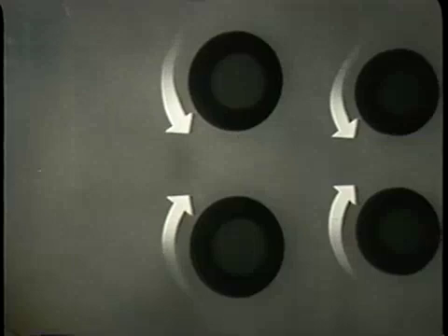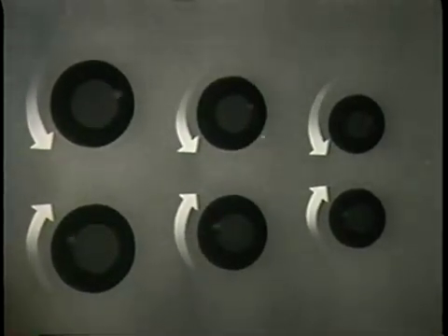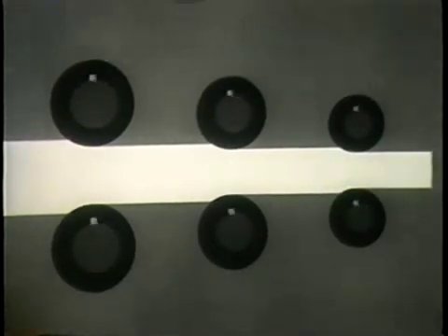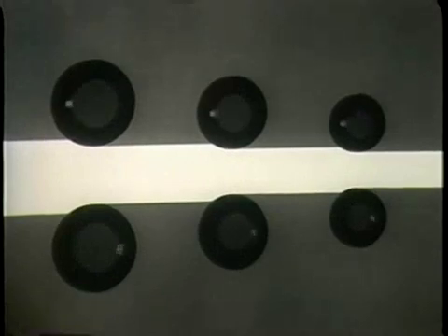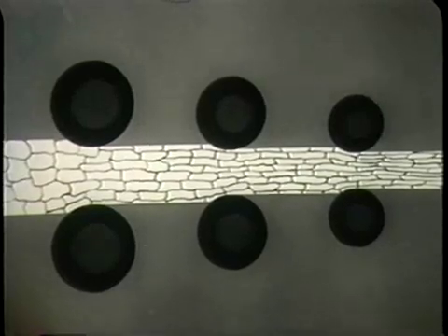A pair of oppositely driven cylindrical rolls is the mechanical basis of the cold rolling process. A series of such pairs of rolls is used, the roll opening of each pair becoming progressively smaller. The passage of the ingot through successive pairs of rolls reduces the thickness of the metal. In the process of cold rolling, the equiaxed grains are flattened and elongated.